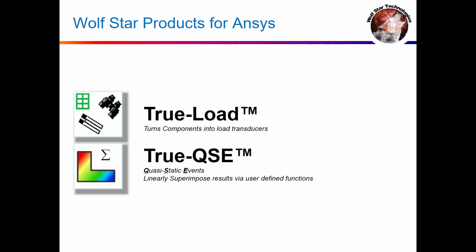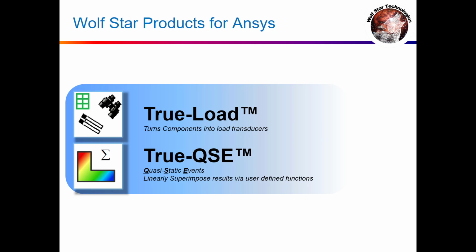And then we also have True-QSE. QSE stands for quasi-static events. Quasi-static events are basically load cases from the FEA model that are linearly superimposed by user-defined functions. And this by itself is great, but what happens is that when you run True Load, it will basically generate time histories of loading that correspond to the load functions in the load cases in your FEA model.